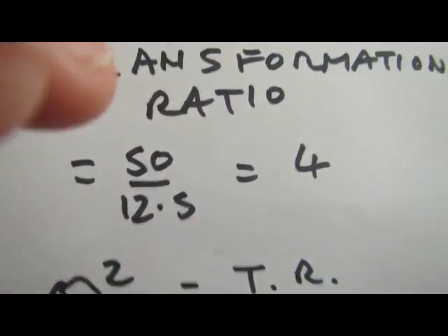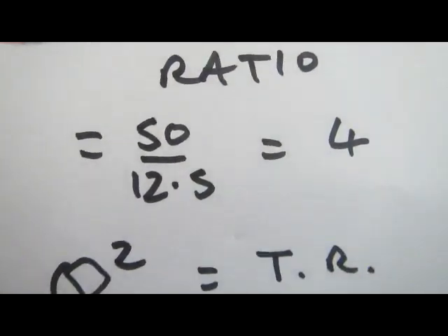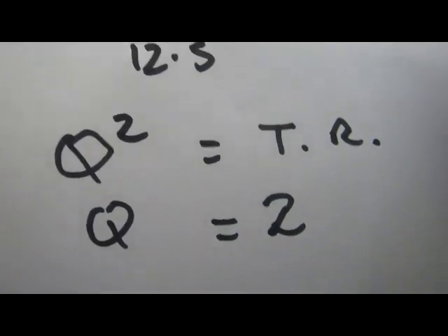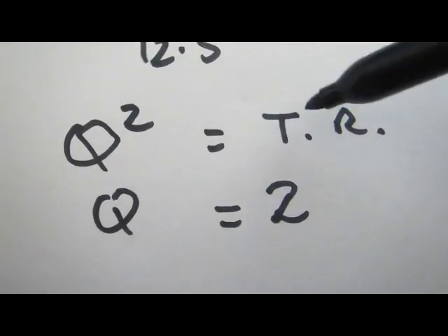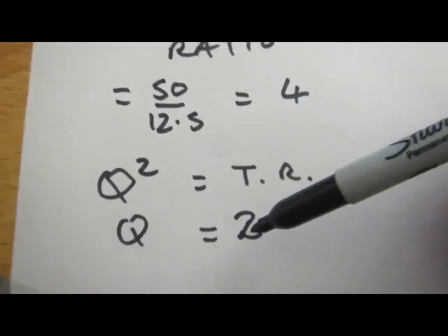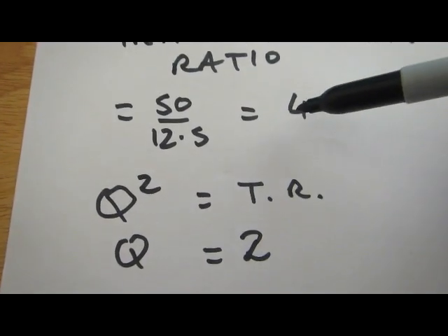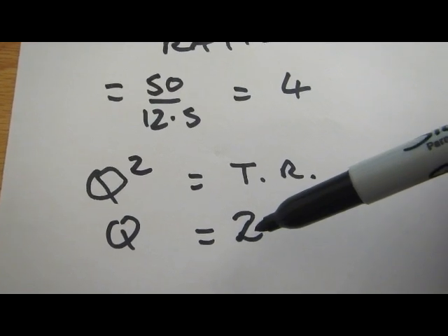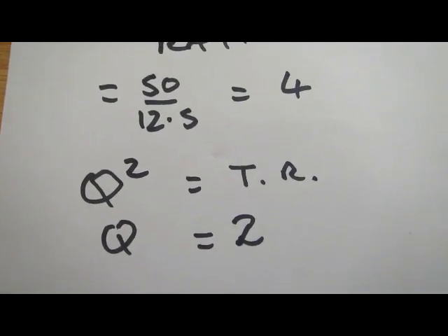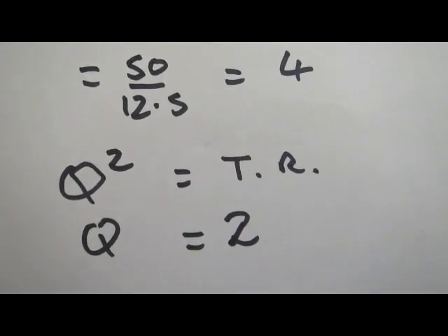And then the working Q of the reactances we're going to use, that's the next thing to get. Simple. The Q squared is the transformation ratio. So the Q equals the square root of the transformation ratio. Q is 2. So when we start looking at our network, we want everywhere to define a Q of 2.